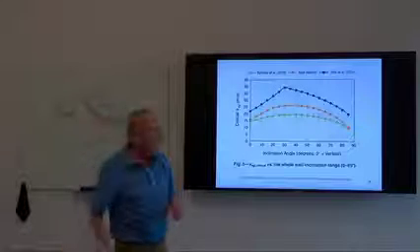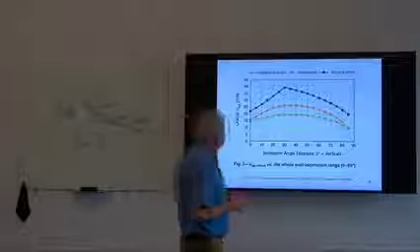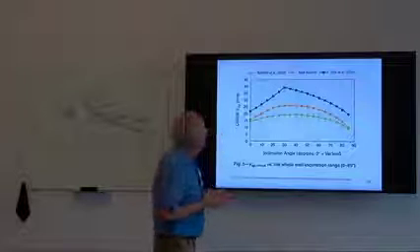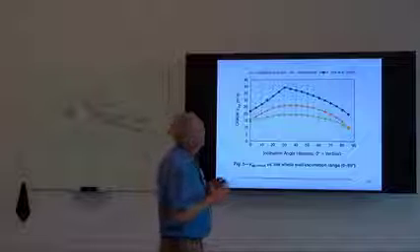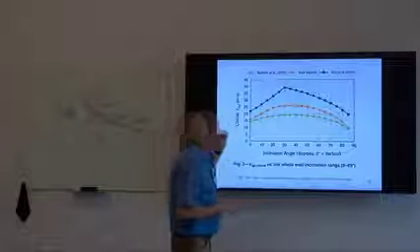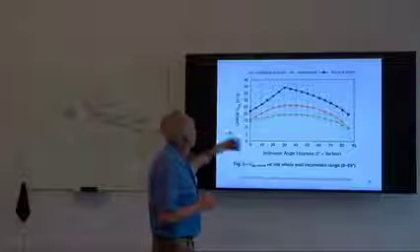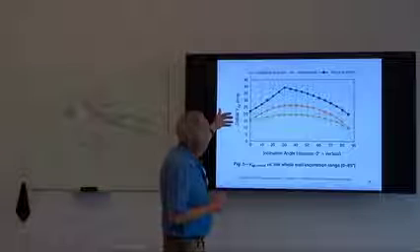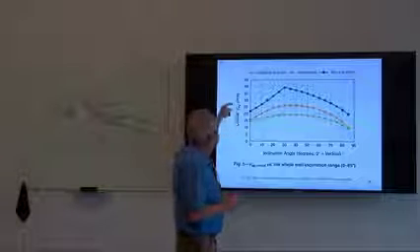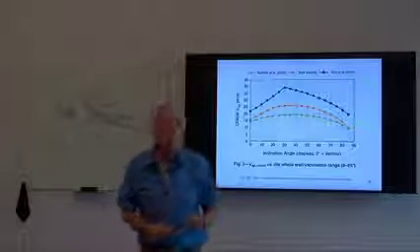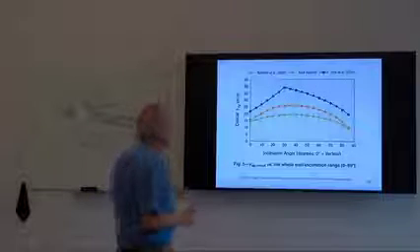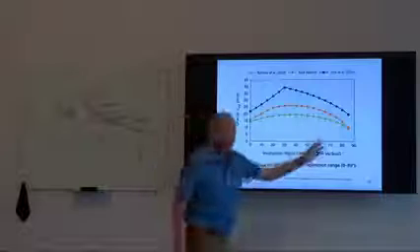And there have been various attempts from different researchers to come up with multipliers of the critical velocity, or in this particular case, predicting the actual critical velocity, not a critical rate, mind you, but a critical velocity based on the inclination angle.